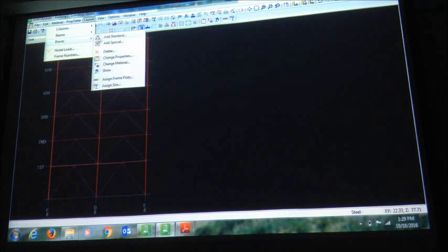At the same time, even though I have not defined any of the column shapes or beam shapes because they will be designed, for the braces, since it's a lateral member, I have to give a size. Otherwise, it will give you a warning. Okay, no, actually, it will give me an error sign. Let's give a brace size. Assign size.